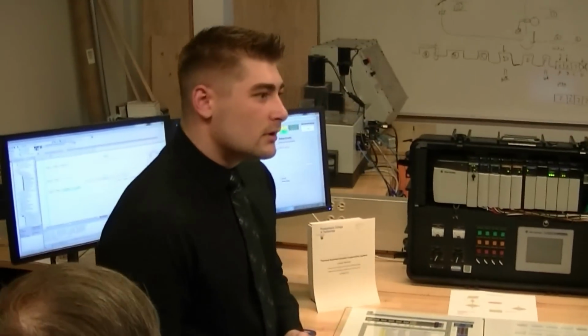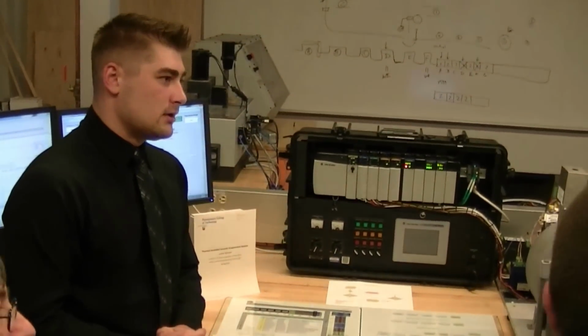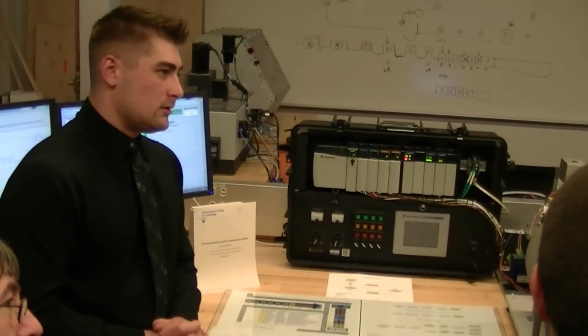So how would you build overpressure? You're pulling a vacuum now, right? No, right now, no. When the vacuum pump was running, yes, you were pulling a vacuum. So how would you overpressurize? If the flow rate of the gas valve would be greater than the suction capacity of the pump. Okay. Or if you start to generate steam off your wet ceramics.